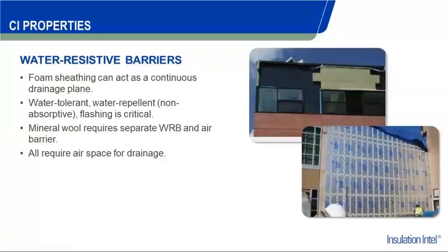If you recall, we just referred to taping the joints of a board. This is an example of this job being taped with the joints being abutted together, but they're also taping over the fasteners to prevent any air or water from being able to penetrate the system. In this scenario, you'd also want to tape any penetrations or seal off any penetrations as well, so that you have everything encapsulated.